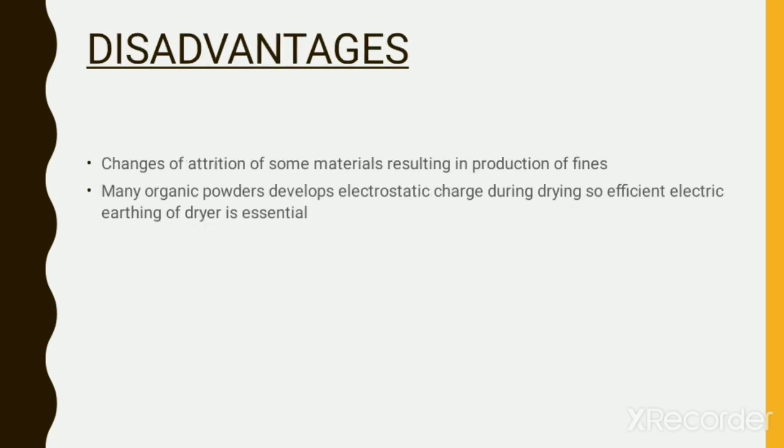Next, disadvantages. First, changes in adhesion of some materials result in the production of fines. And second, many organic powders develop electrostatic charge during drying, so efficient electric earthing for the dryer is essential.